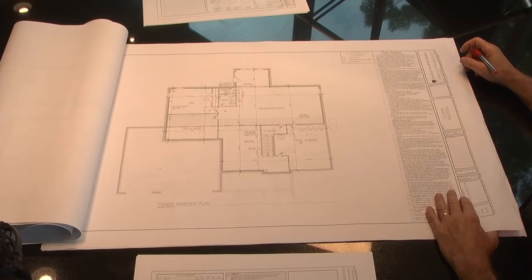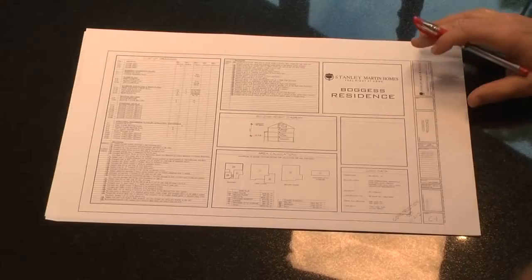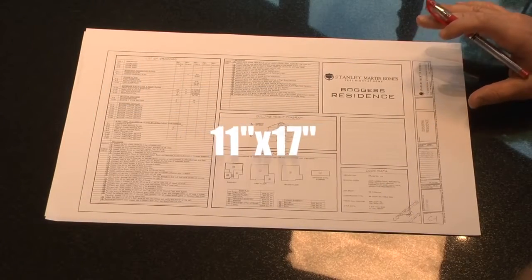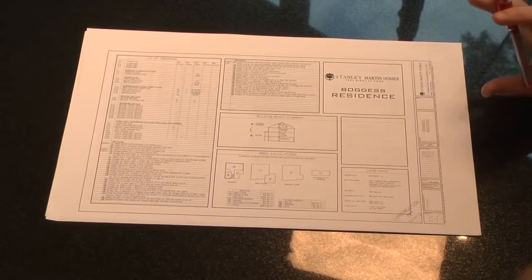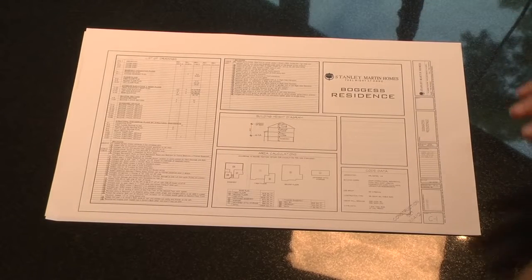Very easy to read, but based on today's technology, none of the trades actually use quarter scale plans. This size plan is still submitted to the county, and this is what we use for inspection purposes. Other than that, there is no purpose to the 24 by 36. So 11 by 17 is used by all trades, all subcontractors, all suppliers. This is the norm in today's building environment.